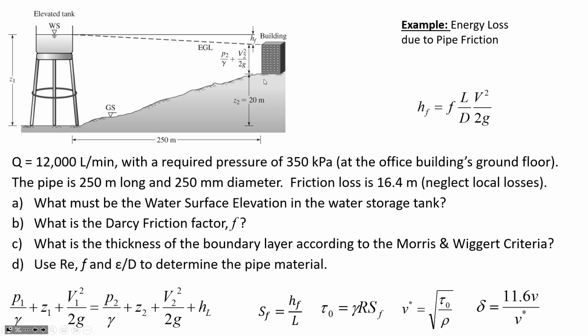Since I'm dividing by newtons per meter cubed, I actually need it to be 350,000 newtons per meter squared. So if you always get in the habit of including the units when you do numerical substitutions into a formula, it'll take just a moment longer as you write it on the page, but it'll pay big dividends in capturing mistakes where the units weren't going to work out.